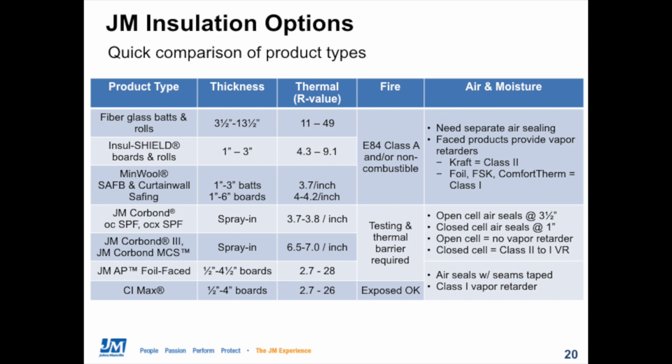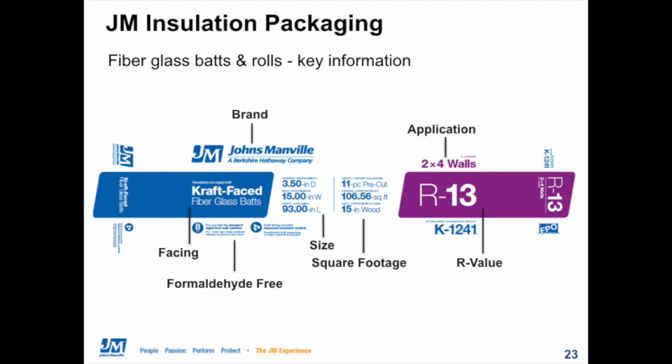Thank you. What are the good, better, and best products for sound control? For sound control, as we touched on briefly earlier in the talk, porous insulations like fiberglass, mineral fiber, and open cell foam are really what we want to use. We want materials that will absorb sound well. Closed cell foams, as their name implies, are pretty closed off, so they don't absorb sound, and they tend to be a little too rigid for good use in noise control applications.